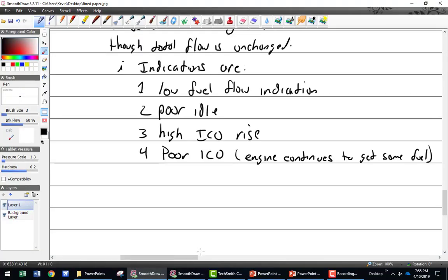All right, we're talking about the RSA fuel injection system. And when we left off, we were talking about the fuel nozzles. Fuel nozzles are a fixed orifice. And the more pressure I try to put through a fixed orifice, as the PSI goes up, what happens to the flow? The flow increases.